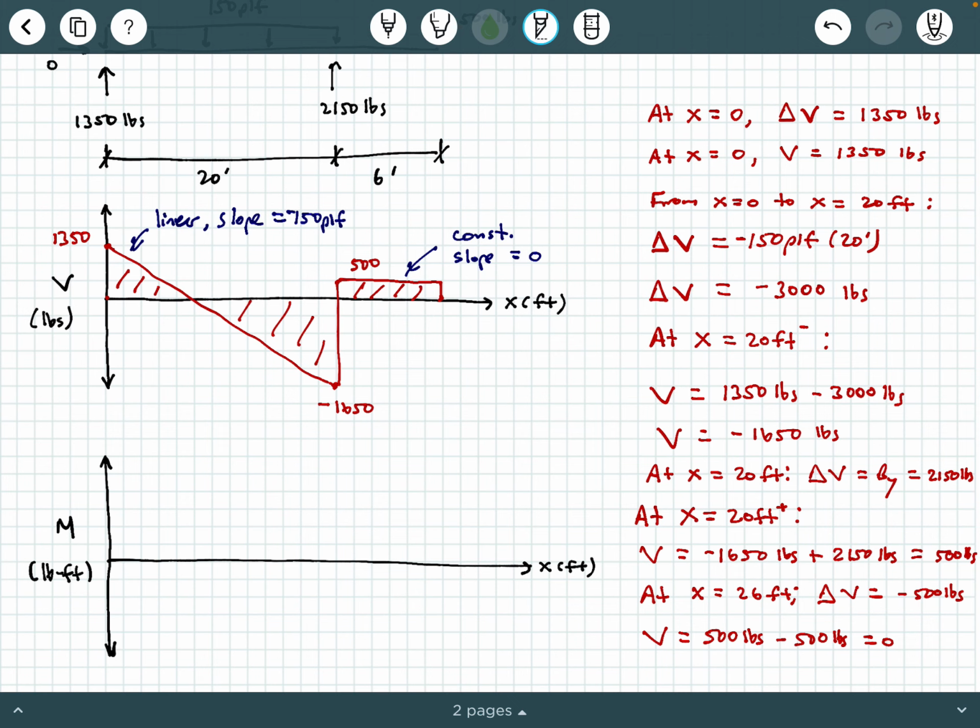So what we need to do now is use similar triangles to figure out what are these dimensions here, okay? So I'm going to do that. I'm going to call this dimension A, and then I'm going to call this dimension here 20 feet minus A, okay? And I'm going to use similar triangles with these two triangles. They're similar because they share a common angle here and here. And I'm going to solve for these dimensions A and then 20 feet minus A. And the reason why I need that is I need to be able to calculate these areas, all right? So I'm going to do that in green, and I'm going to do it in this kind of open space here just so I don't have to scroll as much.